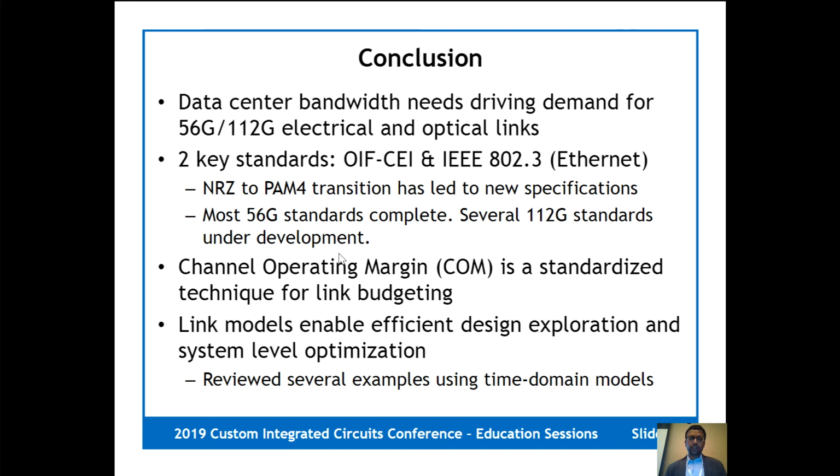And then for link budgeting, we looked at the channel operating margin and saw how that can give you a standardized way to determine what your link budget needs to be for an electrical link. And then finally, we looked at some link modeling and examples of how they can enable SerDes architecture exploration and validation.